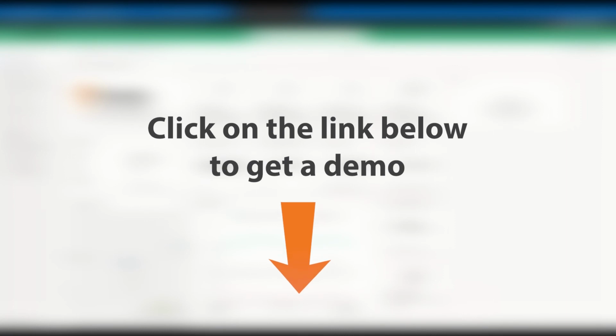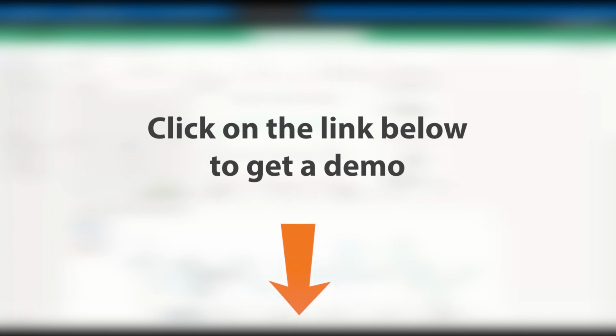So we have created a dashboard here called Water Metering Demo. And an example here is, if you're familiar with Lightweight M2M, there are object IDs and resource IDs. So we're looking here at a particular object ID. This is a pressure reading: object ID 3323 and the resource ID of 5700.